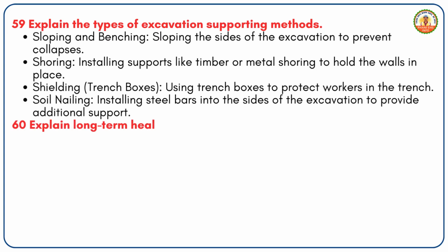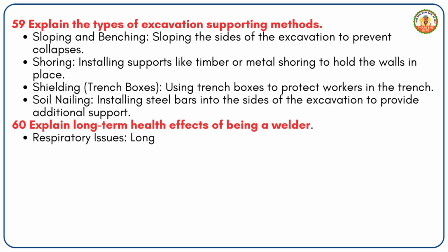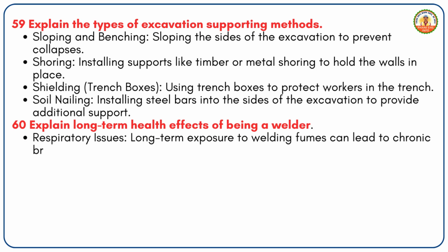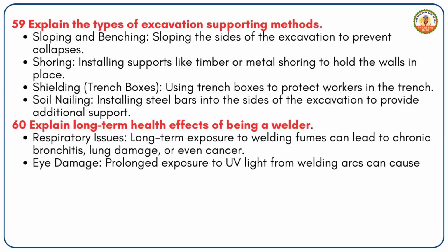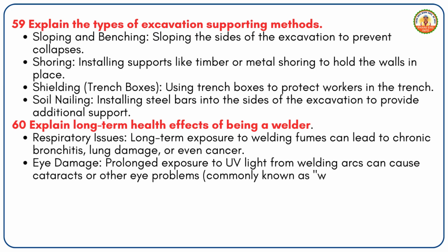60. Explain long-term health effects of being a welder. Respiratory issues. Long-term exposure to welding fumes can lead to chronic bronchitis, lung damage, or even cancer. Eye damage. Prolonged exposure to UV light from welding arcs can cause cataracts or other eye problems, commonly known as welder's flash.